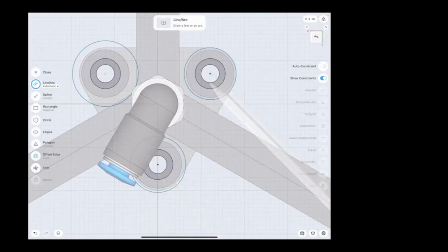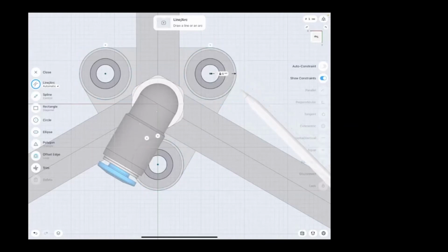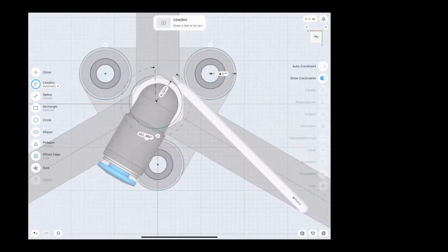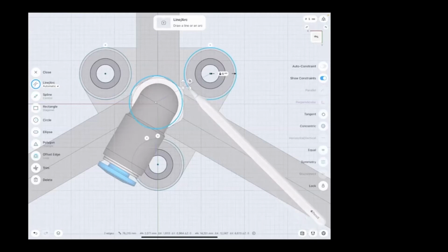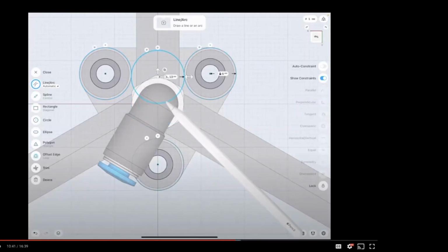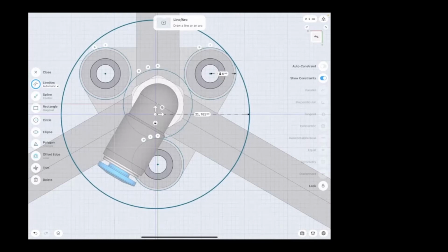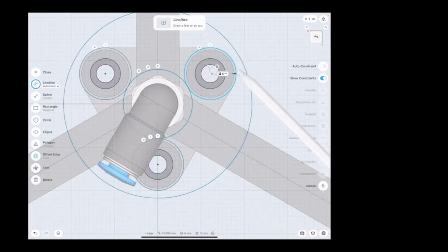And after locking those together and constraining the radius to be equal on these 3 circles, I will set one radius to be 6 millimeter. Then I will need a 4th circle, to make sure that I will have enough clearance in the workspace between the parts. And then I will need a 5th circle to make sure that I will have enough material thickness.